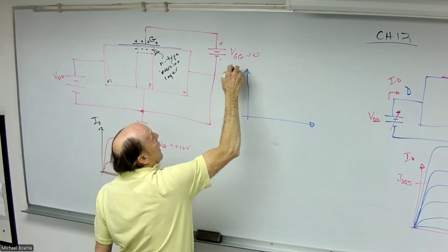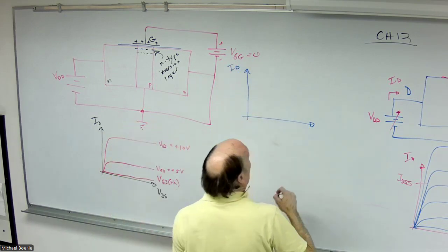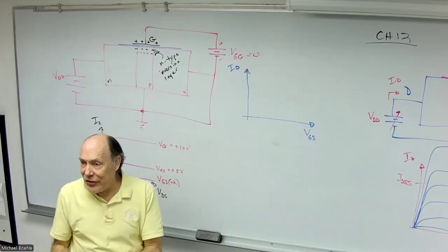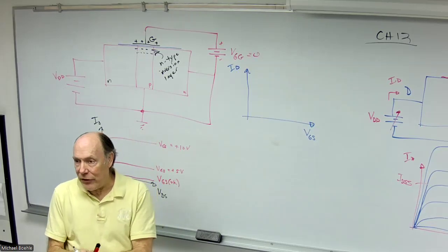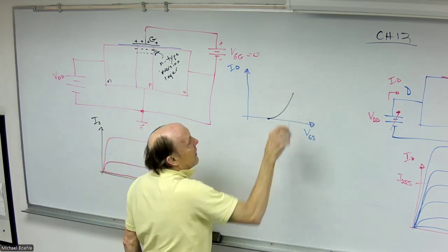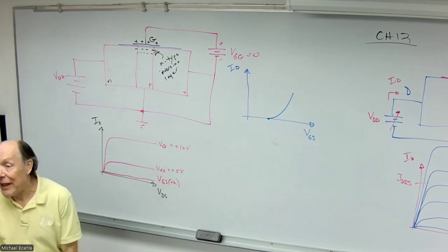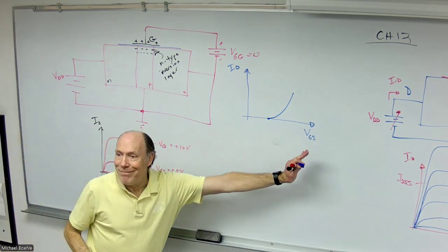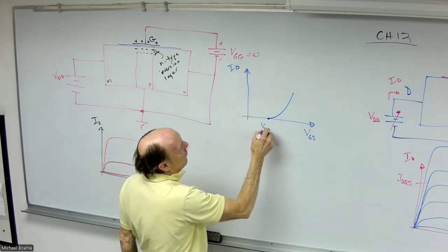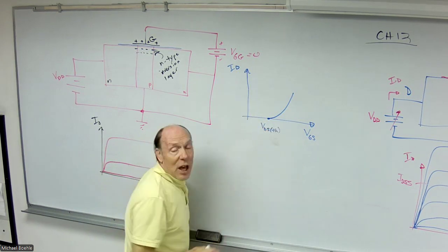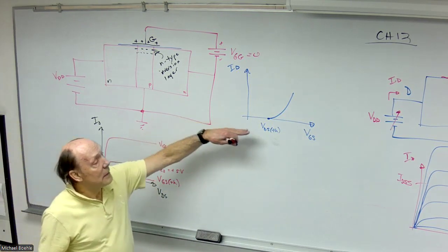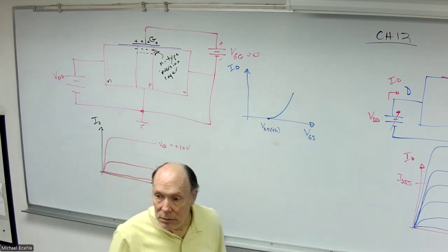If we look at the amount of drain current that we essentially saturate at versus the gate source voltage, this is still a square law device. You still get that shape of curve. It's shifted over. The point at which the current begins to flow, again, that is my gate source threshold voltage. Once I get beyond that, I have my square law.